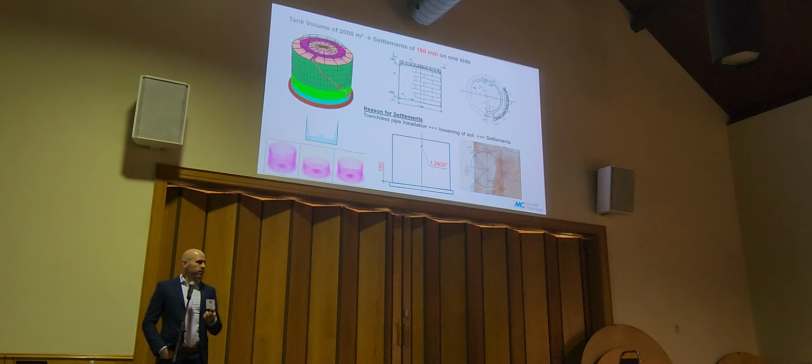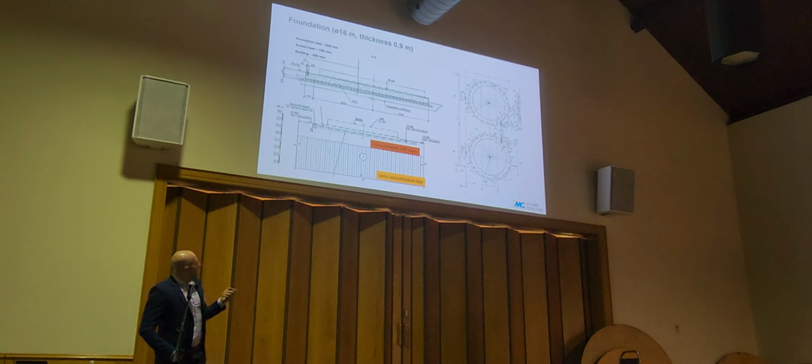And now the question was, okay, how to get rid of this problem? First idea was, okay, we will go there with a compensation grouting and lift it up by cement. The problem was that this job site itself was not the only problem. They had also some weak layer of clay below this tank. This was the construction itself.